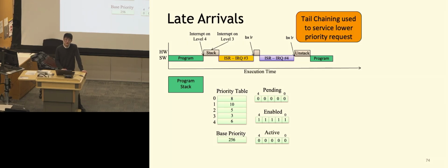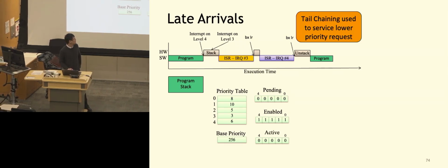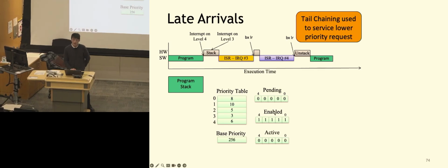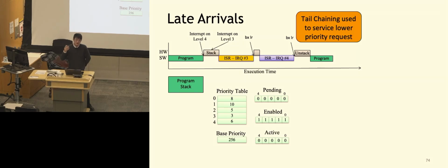Interrupts, I see. Yeah, the enables for the interrupts are independent from the core, whether it is stacking or unstacking. Those bits are hardware registers that correspond only to each of these interrupts, to show whether they are able to be active, so to speak. They don't have to raise any flags, or have an interrupt request, but they're able to make an interrupt request if they want to, if that makes sense.